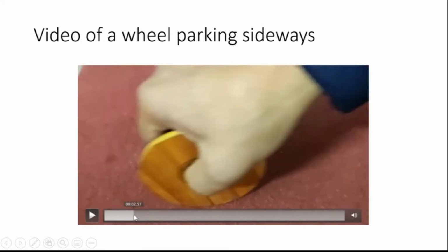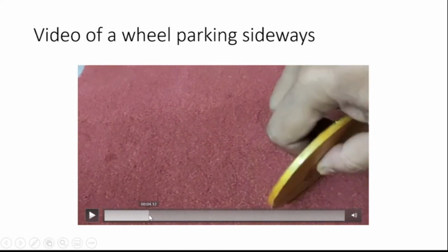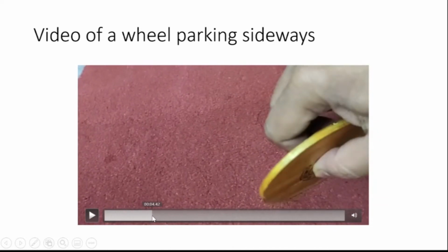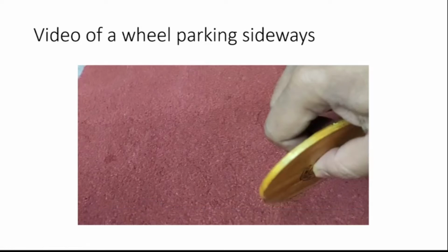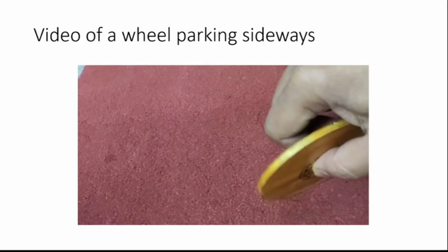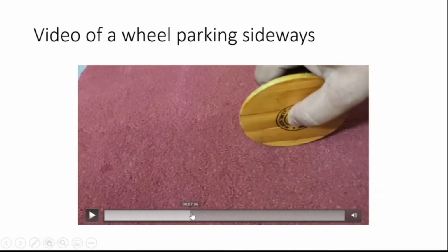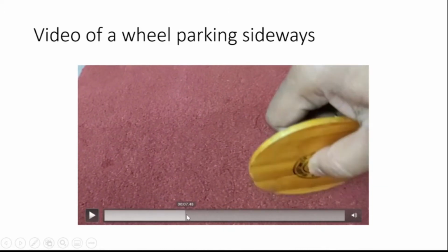This wheel can move forward and backward, and it can rotate about its axis, which is the steering actually. If you see a car made up of 4 wheels, each front wheel can be thought of like this, and a unicycle is the same wheel that is being shown in the video here. It cannot go sideways because of that single non-holonomic constraint.